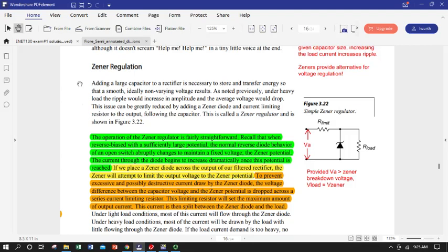This is a follow-on to our discussion of full wave rectification in our previous lecture, in which we discussed both center tap and bridge rectifier styles and the advantages of a full wave rectifier in that it didn't throw away one half of your input waveform. So you basically ended up getting double the frequency in your output, you retained the whole waveform, and from the standpoint of getting true DC rather than pulse DC, you made it easier to correct for that ripple.